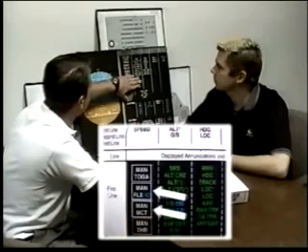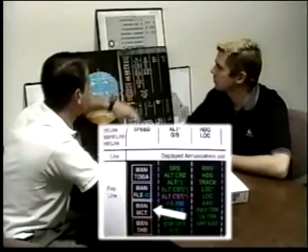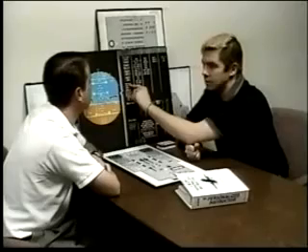Man Flex and Man MCT are the same detent, so how would I get Man MCT? Man MCT is only in flight. Okay. Would that be a single engine FMA? No, it's 2 engines, and it means that the auto thrust is armed and the most forward thrust lever is in the MCT detent. If I were single engine and I had that same situation, it'd be engaged, because the engagement range changes to the MCT detent instead of the climb detent.